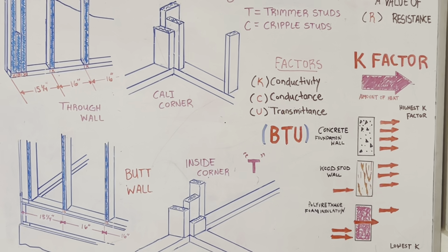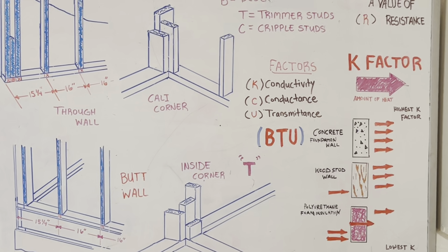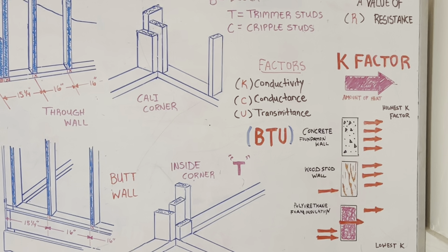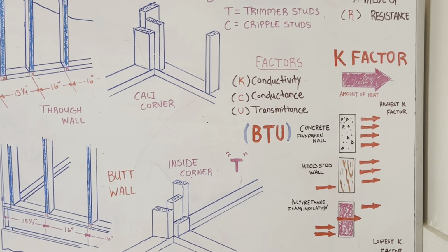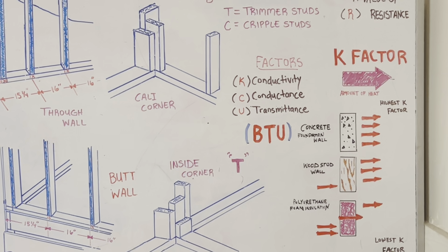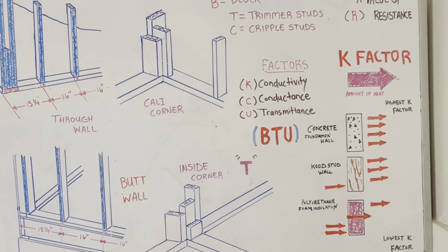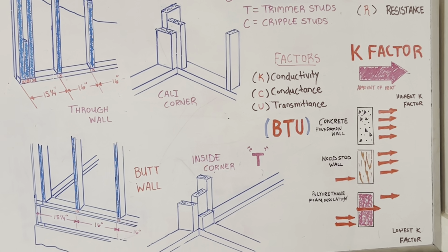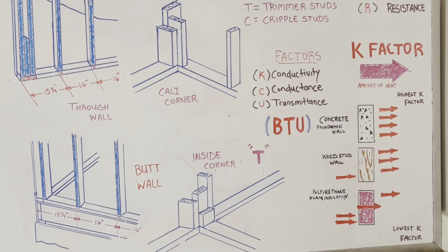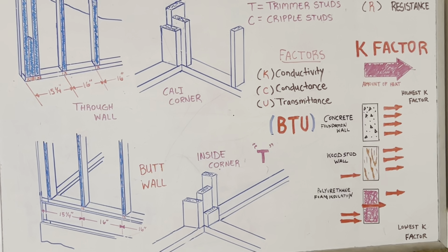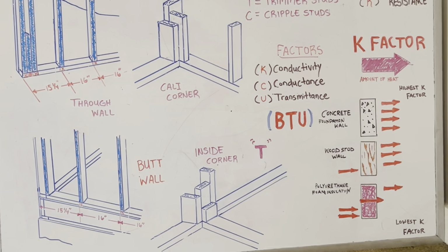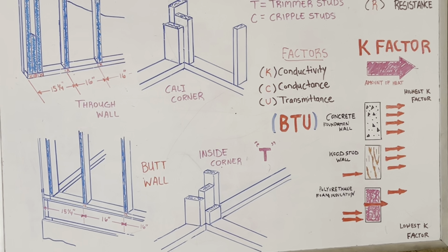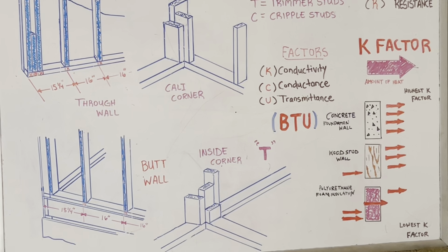The total heat flow resistance of a wall includes the R value of the material used to construct the wall, such as wood, brick, concrete, or hollow concrete masonry units, plus the R value of the insulation material placed in the wall. An airspace, such as the kind found between a wood frame and brick veneer wall, adds to the total R value of the wall.